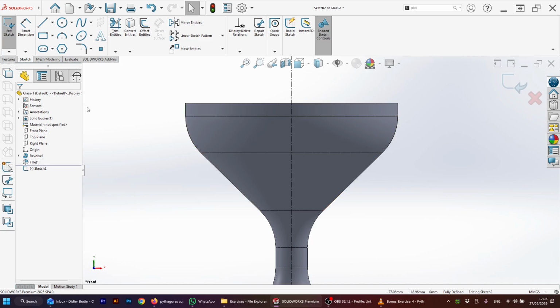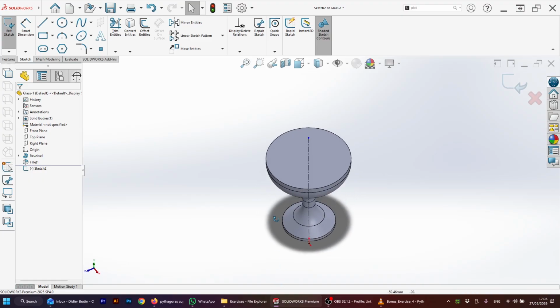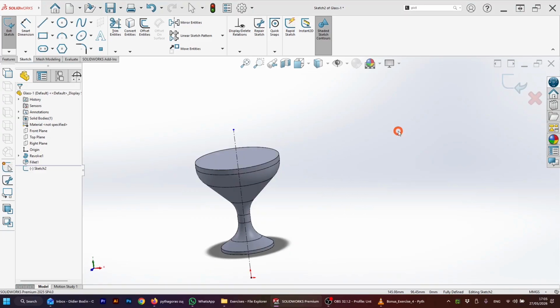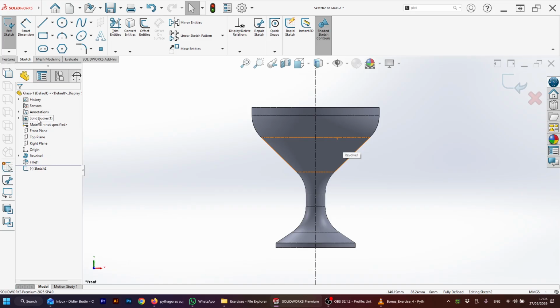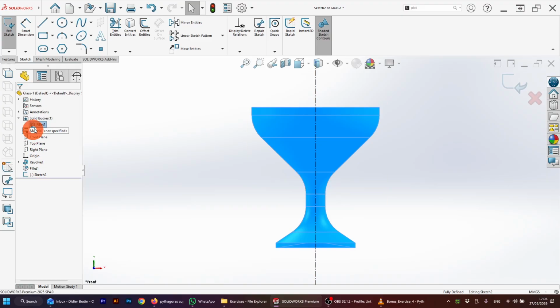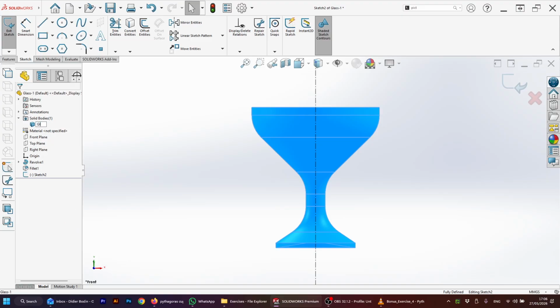So right now we are using the shape that we are sketching in the middle, on the edge of that cup. The software is going to give it to us automatically. In order to do that, I click on solid bodies. There is a little arrow. Click on fillet. That's the name for now of these bodies. We could rename it to something else. If I want to rename this, normally I can rename the item. I can call it glass. You see now it's there.